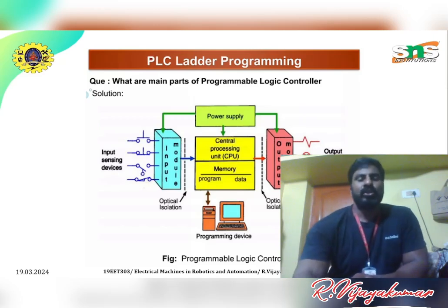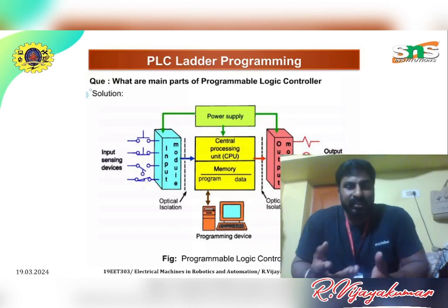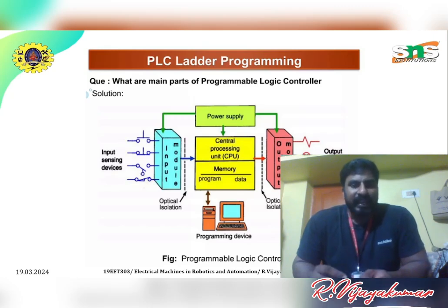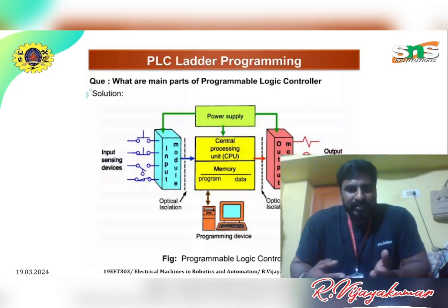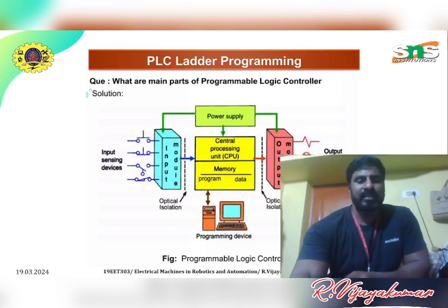Ladder diagram is a high level graphical programming language that is designed to look like an electrical schematic. Because it is a visual language, it is very easy to understand and debug ladder diagram code. Ladder diagram makes it easy to program and monitor complex Boolean logic, which is exactly what it was designed for. Here you can see a ladder logic diagram, for example, with inputs and outputs.